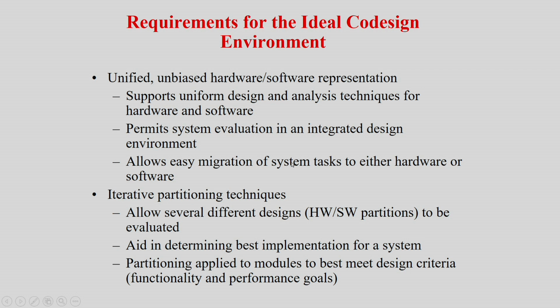So if I can give you an environment where I can write the hardware in Verilog or VHDL, and I can write the C program which has to be running on that hardware, in the same environment I can code, and the simulator will take the C language or whatever language you have written the soft code in, take each instruction of that, map it onto the hardware which is still in a soft language like Verilog and VHDL, and finally it will tell you how the hardware will behave when such instructions are taken into picture. So that is actually called a unified or co-simulation environment. That is a big challenge to design. In fact, it's very challenging to design a very fast working simulator for that.